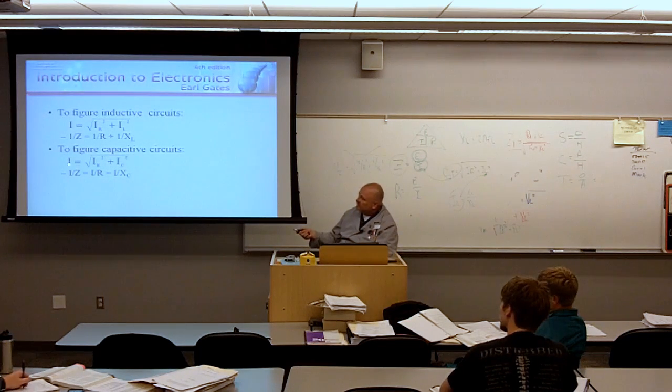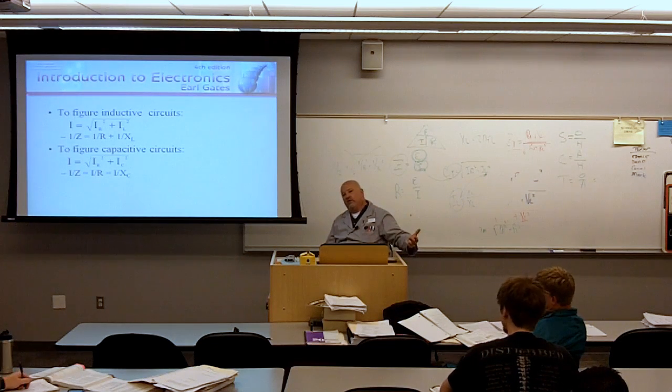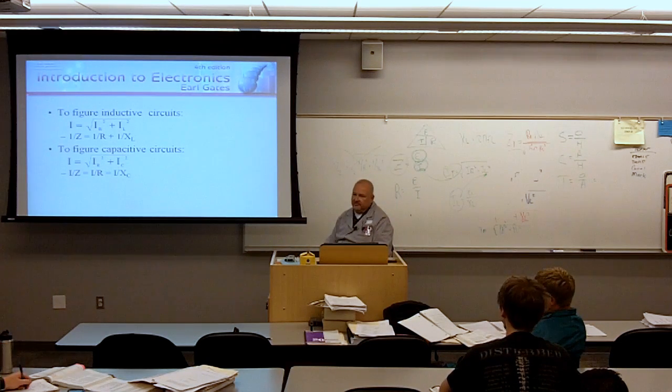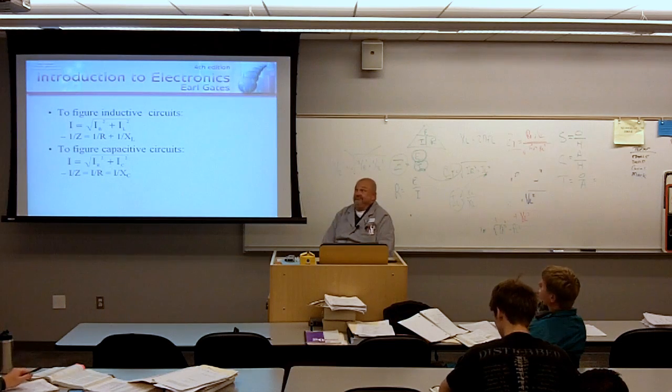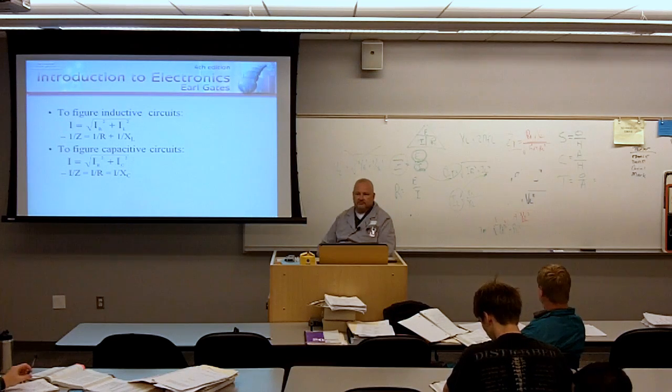What kind of a circuit is this? AC, parallel RC circuit. How do I know that? Because I'm taking the vectoral sum of the current through the resistor and the current through the capacitor. If this were a series circuit, they're the same. Current's constant in a series circuit. Make sense?